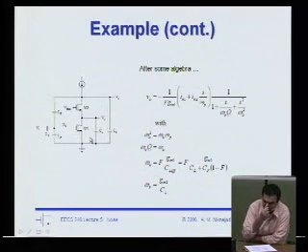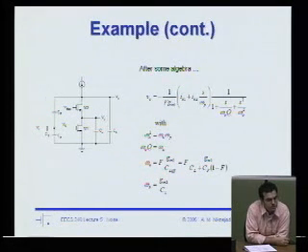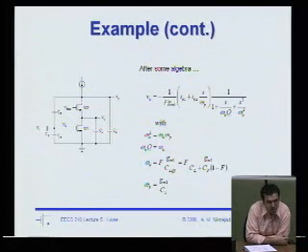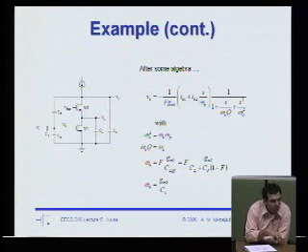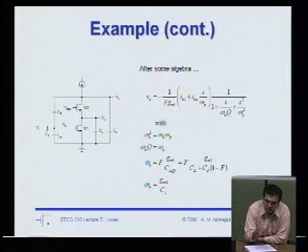Okay? Now, we're not going to intentionally put a capacitor there, right? That capacitance actually represents the parasitic capacitance at that node. So it's the drain to bulk capacitance, the source to bulk capacitance, gate to drain capacitance of M1, and most importantly CGS of M2, right? Now if just for argument's sake, how big is omega p roughly? What's an upper bound on omega p?